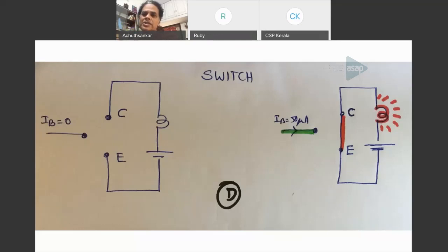Because the signal shapes are the same, you cannot say there is an amplification. So my idea is that you must take this word amplification with a pinch of salt. You are not creating new power and energy. You are only, by a clever mechanism, ensuring that a small change made in the base circuit is in effect obtained in the same shape in the collector emitter circuit. But the energy is not amplified, because then the law of conservation of energy will not be holding. So I just wanted to point this out.